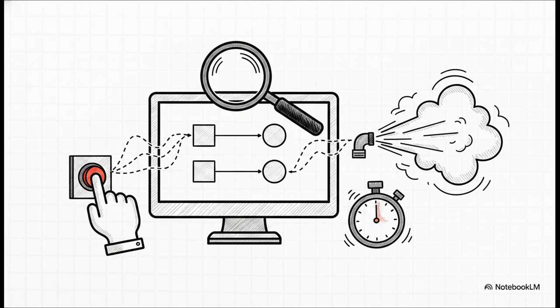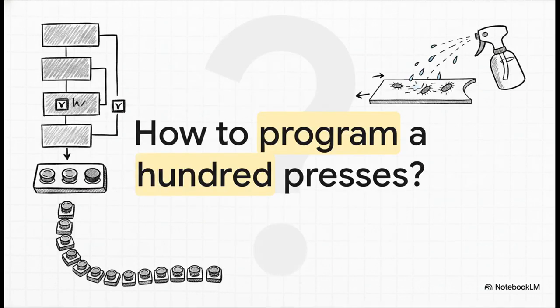And this brilliantly illustrates our success. Right on that fourth press, bam, we see Q0.0 go high for exactly 10 seconds, proving our physical nozzle is finally firing. We just successfully used memory bits and latching to perfectly capture a 4-step sequence. It's a fantastic exercise in understanding state retention.